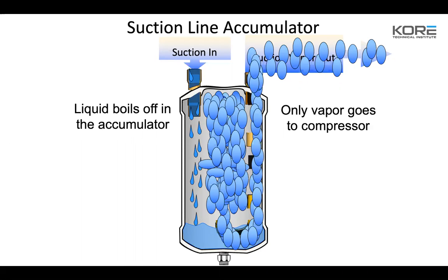So you want to make sure, like in those colder climates, Idaho, Utah, Denver, Colorado Springs, those areas, that anytime we have the opportunity, we get on a service call and you do see ice on that accumulator, take the time just to get that clear, either melt it off or take some time and get that, because all you're going to do is have another service call there in the future. Especially with these cold temperatures that we're seeing already, we might have some floodback issues with our systems, because these things are going to start icing up.